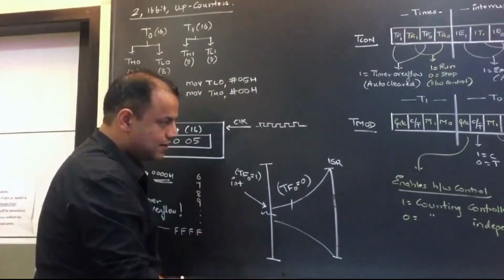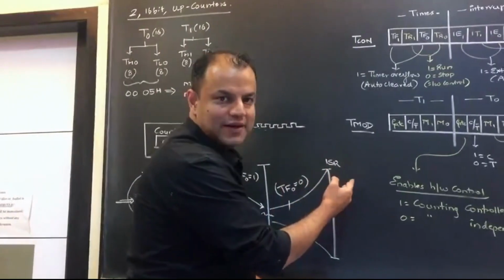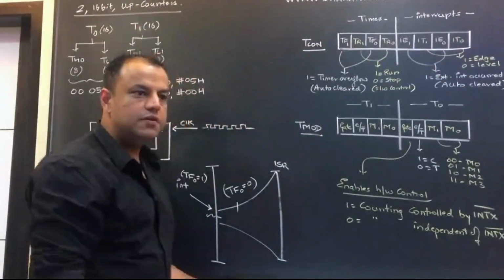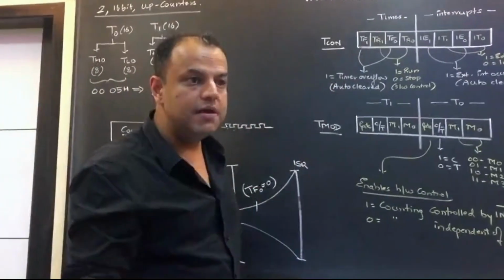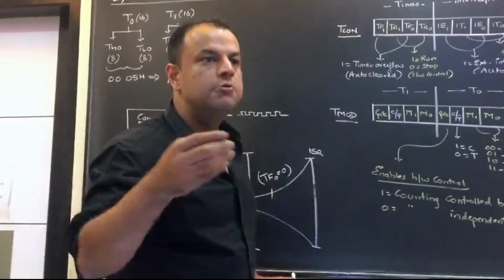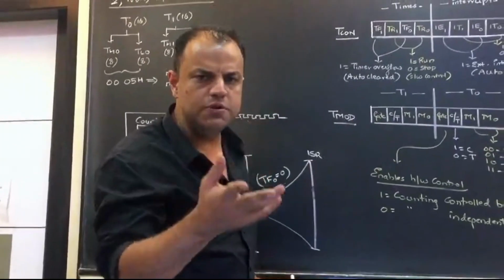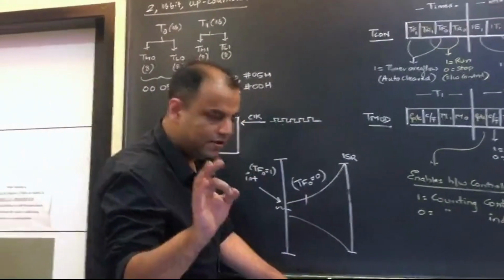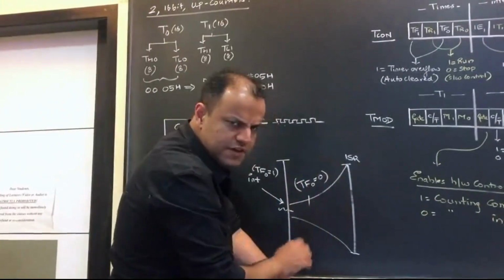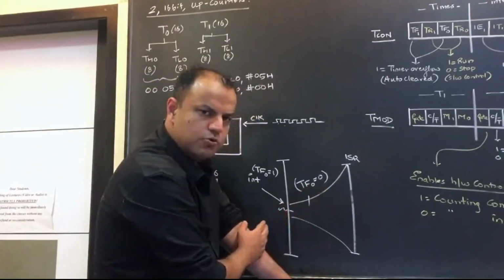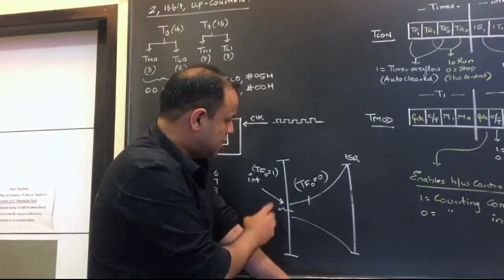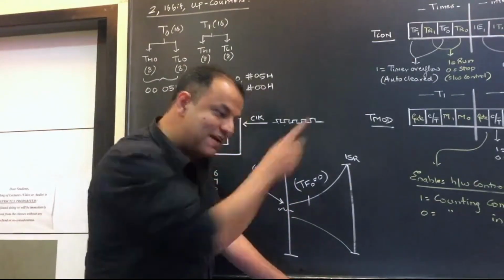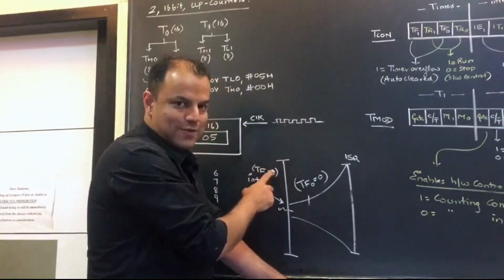It will suspend the current program, go to the ISR, where it will do whatever it wanted to do after the delay. Maybe after the delay you want to fire a missile. Maybe after the delay you want to launch a rocket. Maybe you want to start some shower. Whatever you want to do after the delay, you do over here in the ISR. So my point is, when you finish the ISR and come back to whatever program you were doing, should this flag still remain 1? No, because we went to the ISR because the flag was 1.